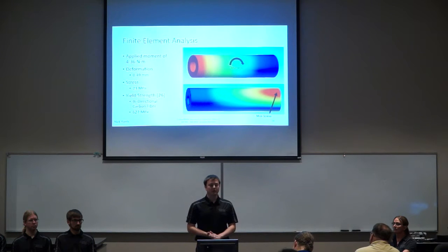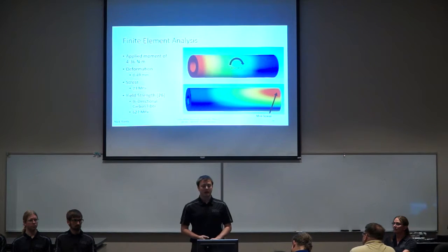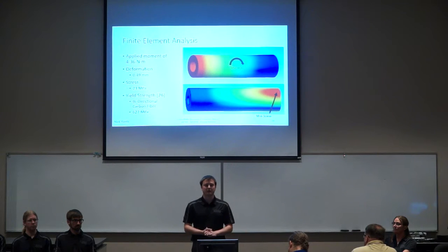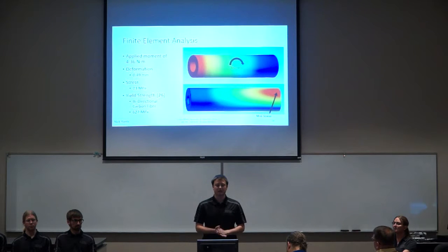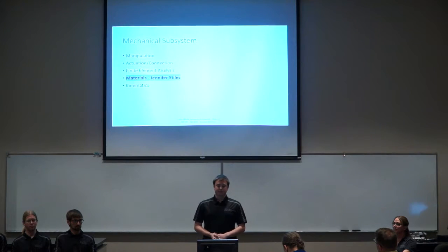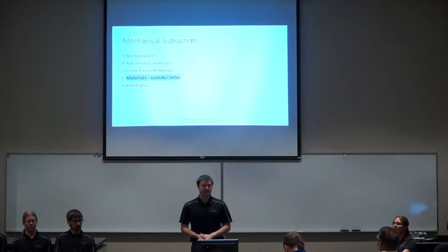And at the max stress point, we got 23 megapascals. Comparing that to our yield strength of 627 megapascals, there's no need to worry about that. But we will also be doing extensive testing next semester because it is a preliminary number, and we need to get actual data from the actual material that we will be using. And now Jennifer will discuss the materials.